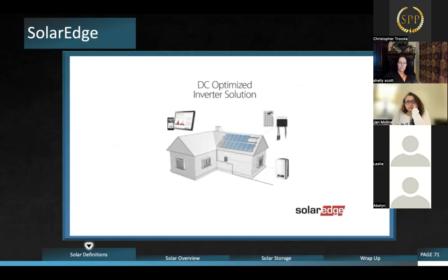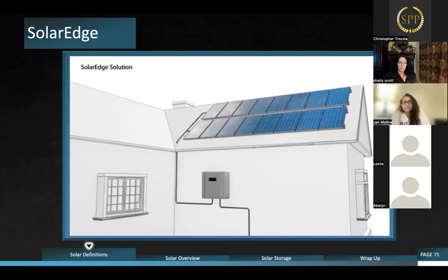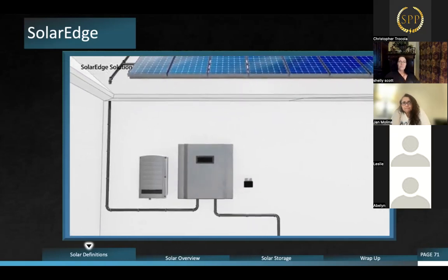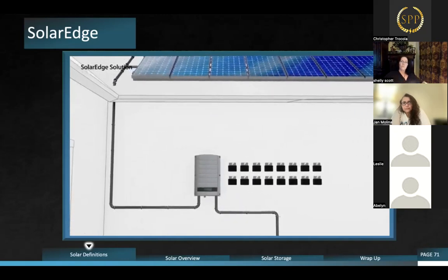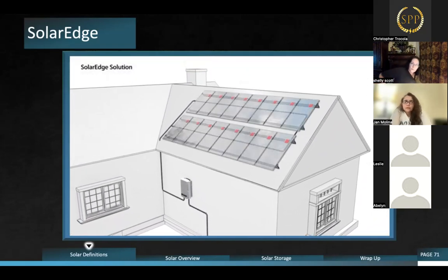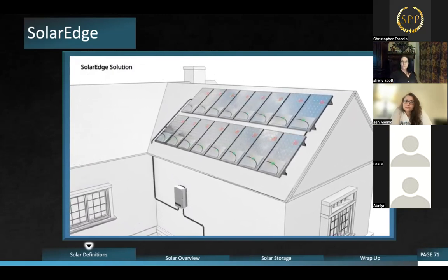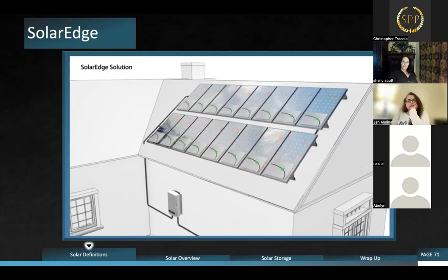Eventually, we developed a topology that meets all of these goals. The SolarEdge DC optimized inverter topology combines the best of both worlds. Our solution splits the traditional inverter functionality into 2 products, the Power Optimizer and a simplified inverter. The Power Optimizers are located on each panel, turning the panels into intelligent panels. These Power Optimizers provide panel-level tracking and real-time adjustments of current and voltage to the optimal working point of each individual panel.